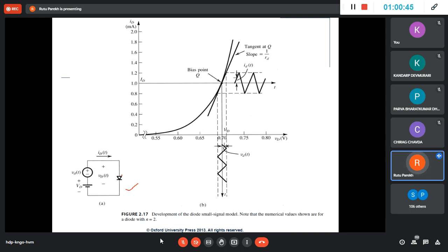So I have to turn on this diode, and to turn on the diode, you give 0.7 volt, and it is on. So you will need a battery to turn it on, and you will set it. If you set it to 0.1 or 0.2, then it is still dead. So you will make it 0.7, the diode is on, and now to that circuit, you will give the voltage of the signal that you want to process.